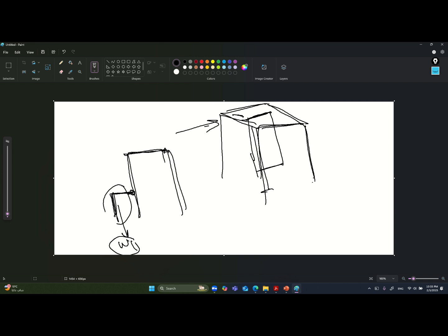Maybe if it is steel, he can tell you what is the minimum force that this connection needs to be designed for. He will give you the statical system of this part: it will be a fixed column, the connection of the beam with the column will be a roller, and with the building it will be hinged. So it is statically determinate, and it is a stable structure.